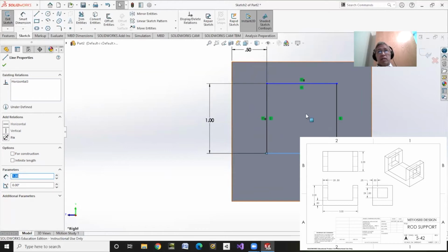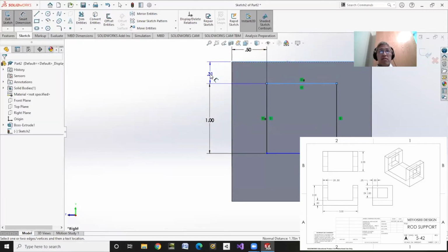So if I want to center it on the top, I'm going to take away the 1/2 inch. That makes this guy from here down to that edge 1.5. I'll subtract my 1, and that makes it 1/2 inch. And then half of 1/2 inch is 1/4 inch. So I will Smart Dimension from the top to the top edge, and that's going to be 1/4.